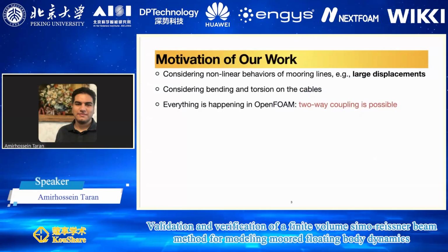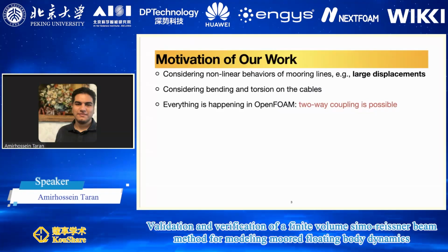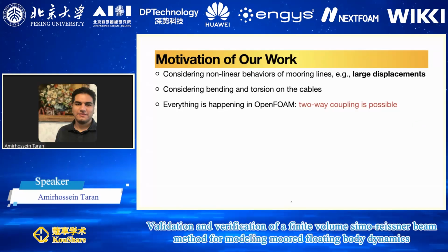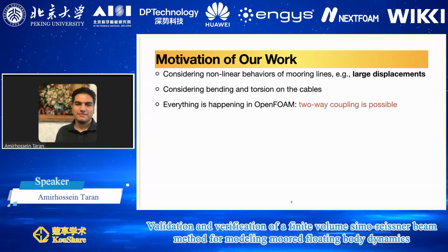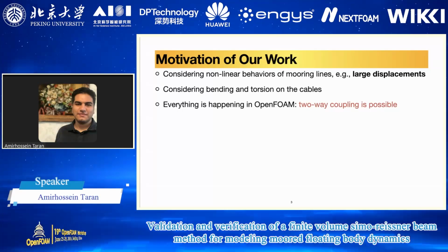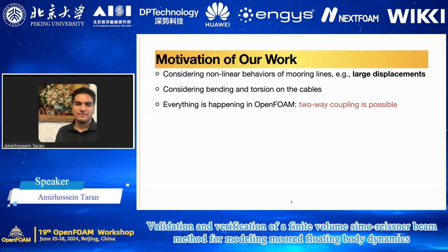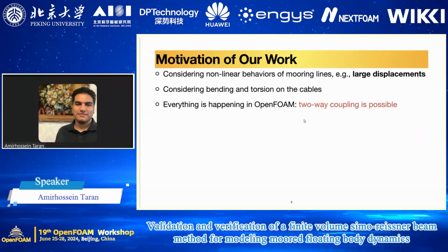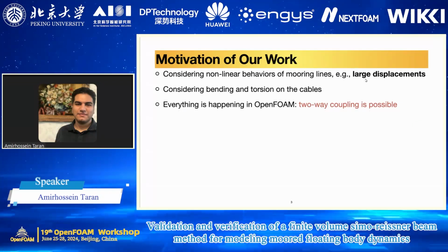So what we are going to do about this is that we have a tool developed in our research group, which I'm going to discuss in a couple of slides later. This tool is able to capture the nonlinearity of a beam, so it can model a beam. Based on the title that you saw, it's called the Simo-Reissner beam theory. It can capture nonlinearities, so you can capture large displacement.